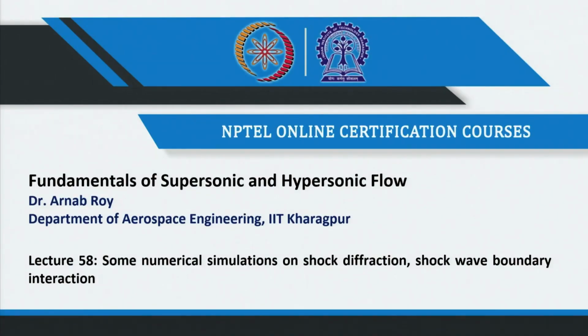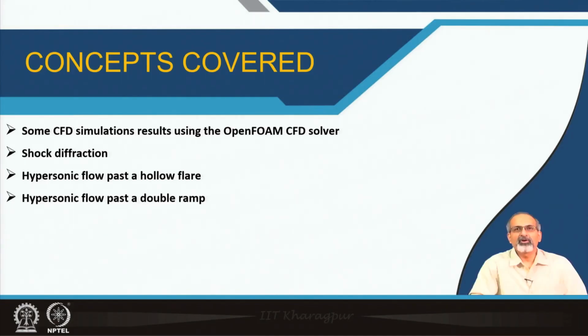In this lecture, let us look at results of some numerical simulations on shock diffraction, shock wave boundary layer interaction. We will make use of the OpenFOAM CFD solver and do some studies on shock diffraction, hypersonic flow past a hollow flare and past a double ramp.